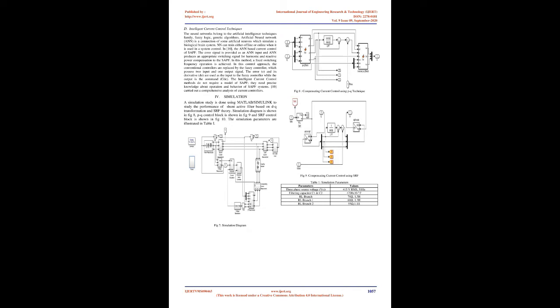B. Synchronous reference frame theory. The synchronous reference frame theory is used to extract the fundamental positive sequence component of the load current by transformation of ILA, ILB, ILC into the dq reference frame. Reference frame transformation is the transformation of coordinates from a three-phase abc stationary coordinate system to the 0dq rotating coordinate system. This transformation is important because it is in the 0dq reference frame where the signal can effectively be controlled to get the desired reference signal.